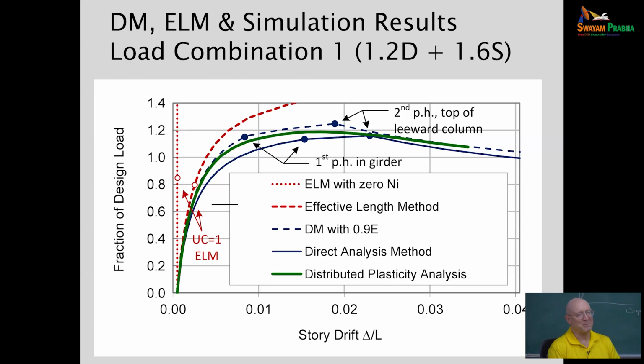So equilibrium, again, what is the mantra? First order elastic analysis is equilibrium in what? Dr. O'Rourke has the sign on his door. Second order analysis is equilibrium in what? Deformed geometry. Okay, first order analysis, oh, we're just doing it on the undeflected geometry. Okay, all right.